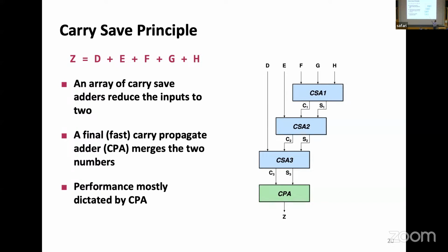And this is one of the greater tricks that we use. We kick the problem down all the way until we can no longer ignore it. And at the very, very last possible moment, we say, okay, I did this for a while. Now it is time. Now we have to bite the bullet. Let's calculate the carry. But it saves me from making fast adders all the way. I mean, this could have been 20 numbers, 30 numbers, 60 numbers. I can just reduce them to a level where I bring it down.